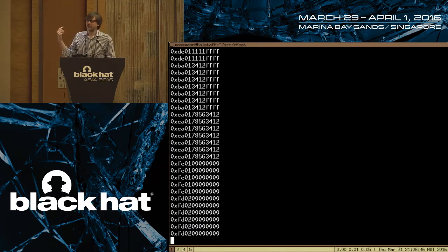When I enter all zeros and then a lock code, which is just 1, I set 1 bit, and you'll notice that the resulting checksum is FF minus 1. Then when I had a nibble that was 2, the checksum is FF minus 2. So it's probably just a subtraction of all of the bytes in a row. So I pretty much reverse engineered the entire communication protocol simply by using a few lines of Python with RFCAT and entering in some codes and figuring out visually what's going on.